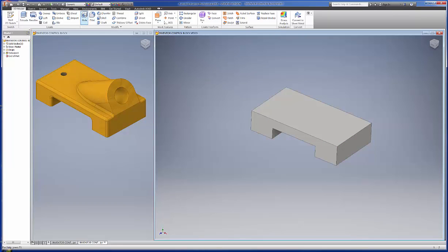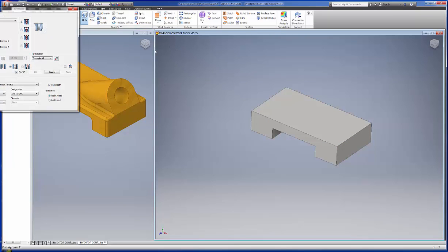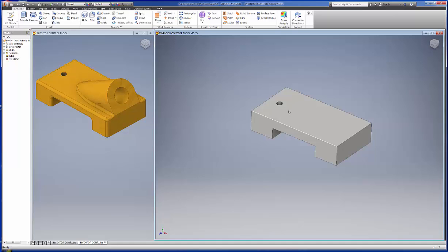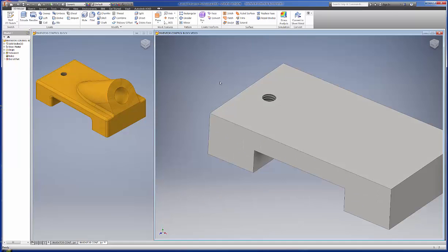Well, something went haywire. Face this first reference, I want to come off of here, and that wants to be 5/8. Again, don't hit enter, and I think it comes off of the back then, 1 3/8. I make sure I've got everything set there now, and it does look like it, and I'll hit OK, and there's my threaded hole, and it's in the right location.